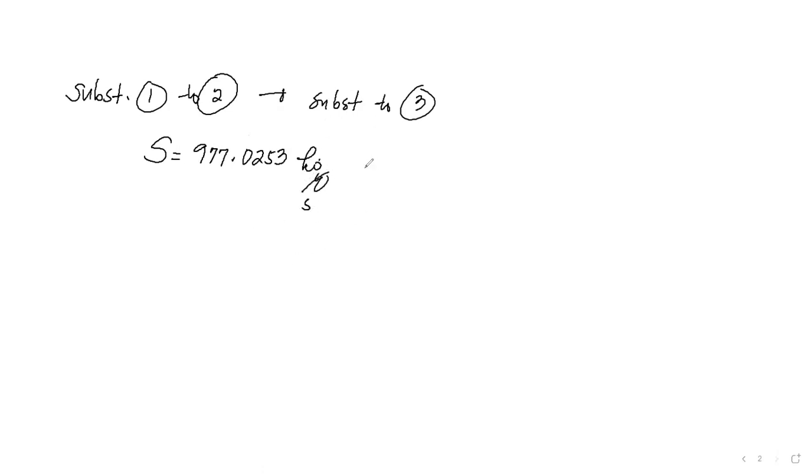Take note that we started with 100 kilograms per second of calcium carbonate, because this is the theoretical amount that will react with your lime to produce your caustic soda, which is 80 kilograms per second, and your calcium carbonate, which is 100 kilograms, but your original feed, which is your sodium carbonate, would be 106 kilograms per second.